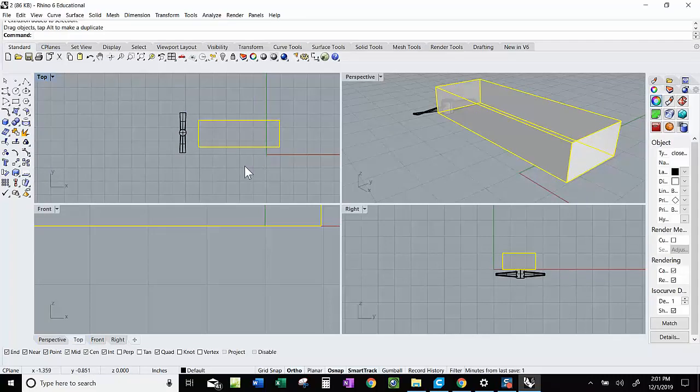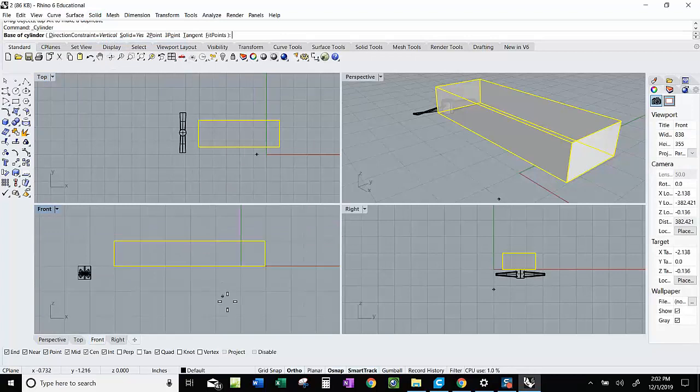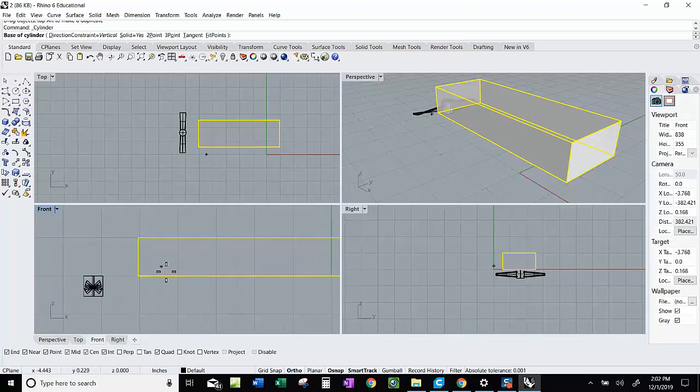That's the chassis all done, except I need to make a hole for the axle to go through, and I also need to make the axles the right distance. So it says here that my wheelbase is 4 inches and the hole for the axle is 0.15. So make a cylinder, and I'm going to look at the side view here. I can make this hole really anywhere here, but my wheels are only 1 inch in diameter, so I need to make this 1/2 inch from the bottom. I can move it around.